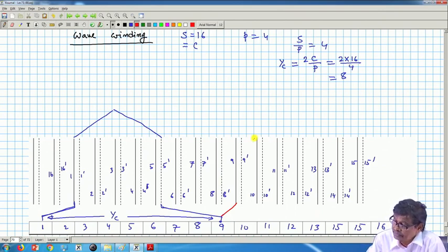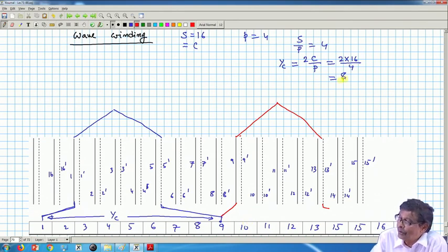It will come over here, but I am not going to terminate it on 10. This time commutator pitch is 8. So, 9 plus 8 is how much? 17, means 1. So, it will be terminated on 1. 1 means here.